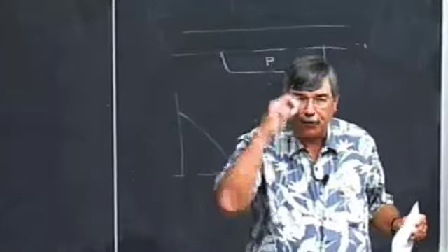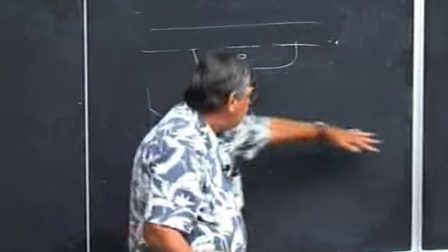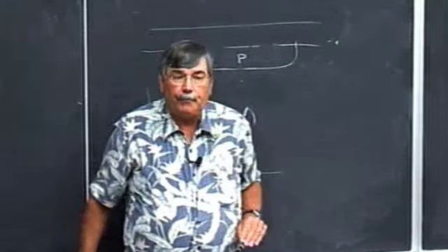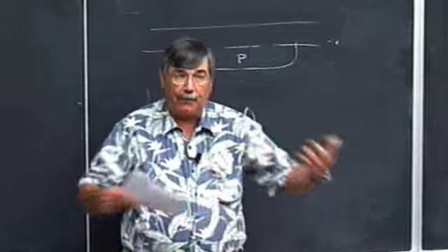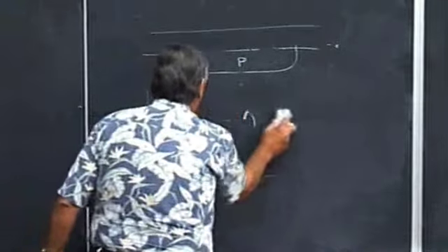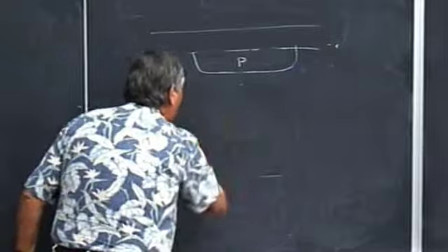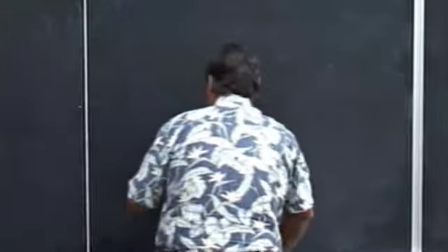All right, different ways to form layers. Now, I'm going quickly through this because this isn't the main point. When you grow the original crystal, you can include impurities and make it p-type or n-type from the get-go, from the time when you created the wafer in the first place. And so you can buy wafers with a particular doping level already built into them. All right?